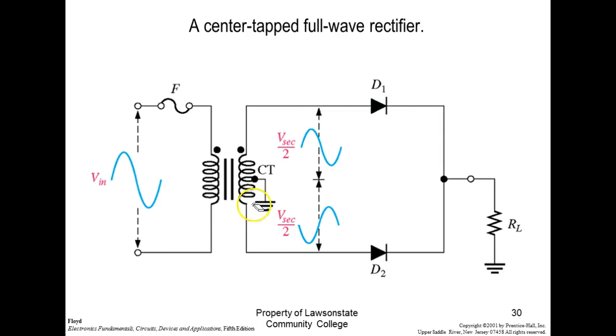So this guy's turned on. The electrons are going to leave this right here. They're going to flow out through here. They're going to flow up through the resistor, so that's going to make this side of the resistor negative. This side's going to be positive. It's going to come up. Why ain't it going to come back this way?